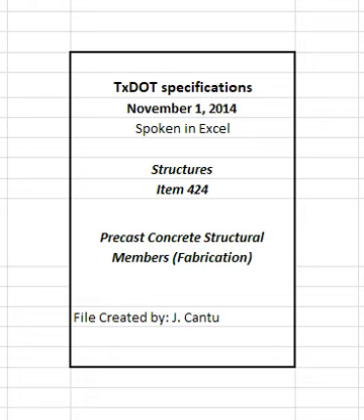Insert a 3/4 inches diameter plastic tube into the top of the void before placing concrete, and leave it in place until there is no possibility of damage from pressure. Remove the plastic tube afterwards and seal the hole with an approved repair material and procedure. Drain precast concrete box beams and U-beams through the bottom flange by forming holes in each voided area as shown on the plans.